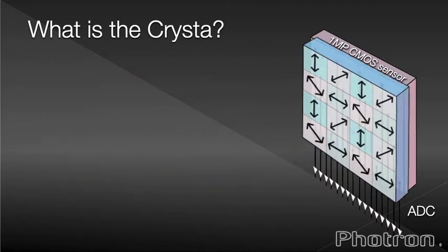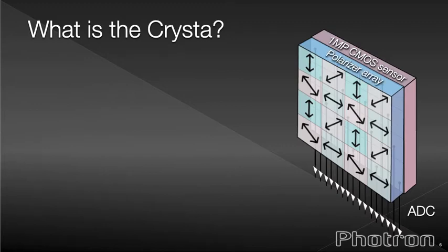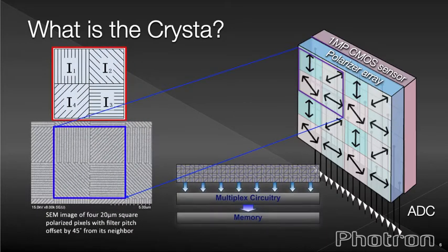Then we sputtered a pixelated polarizer array made from photonic crystal directly onto the sensor on a pixel by pixel basis. This photonic crystal lattice features pixels in clusters of 4 square, with each pixel having a different polarization axis at 0, 45, 90, and 135 degrees. By applying phase shifting algorithms with circularly polarized incident light, birefringence, phase difference, and azimuthal angle can be measured to enable us to quantify and measure physical stress in transparent or semi-transparent solids and fluids in high-resolution, high-speed detail.